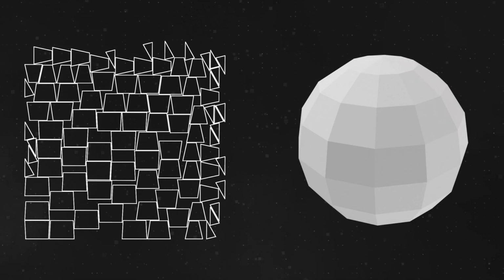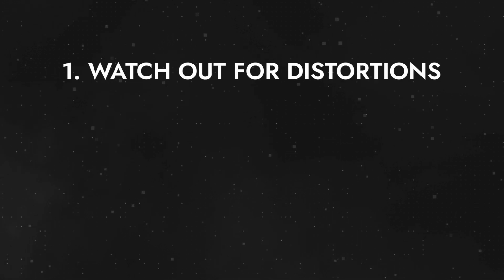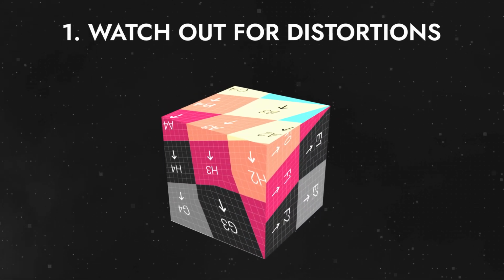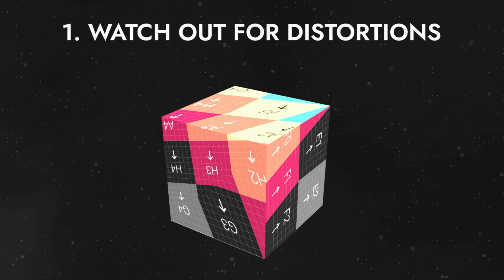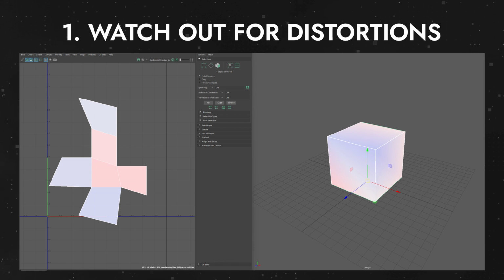There are no technical limitations to creating a UV map. You can cut a model into any number of pieces and place seams wherever you like. However, there are certain rules for doing this better. Watch out for distortions. In a complex geometry with improperly placed seams, a texture you apply may end up looking either stretched or squeezed. The program you're using should have a way of showing how much the UV map is distorted. Seeing this, you can either remove seams, or manually edit the necessary part of the map.